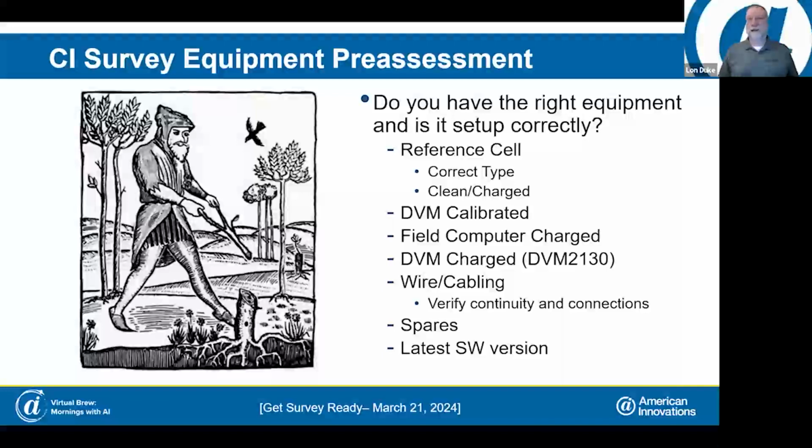Well, I hate to give the old NACE class answer, but it depends, because it does. A lot of that depends on your soil resistivity, high resistivity soil and depth of cover. If you are collecting your data and you know what your soil resistivity is and what your depth of cover is, you can assess that data afterwards and go, yeah, I can see my depth of cover is 8 feet, which is pretty good. In high resistivity soils, I'm not going to get as much.